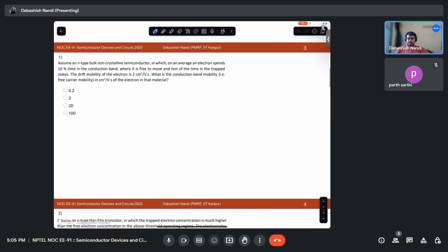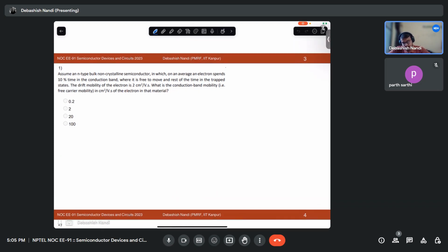So let's begin. The question is about non-crystalline semiconductors. So far we have discussed crystalline semiconductors, right? The periodicity of the atoms in crystalline semiconductors gives rise to the concept of the energy band gap, and those band gaps ultimately link to conductivity modulation by doping, which is the major desired property you want to achieve from a semiconductor.